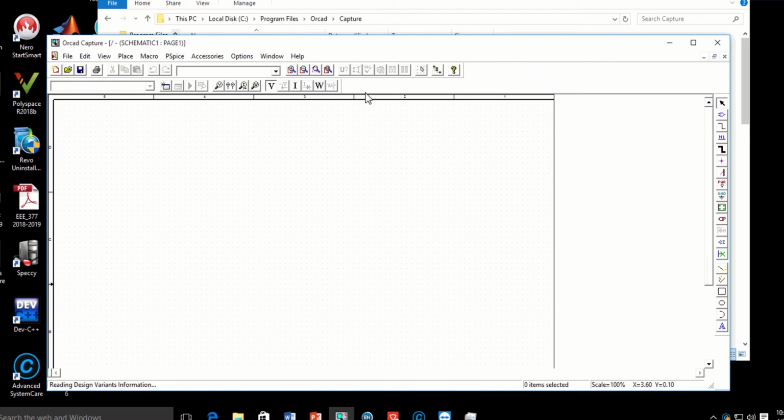Generally, after the first interface is successfully created, the next steps are to place components, connect components, label wires, and run the circuit to perform PSpice analysis. To simplify all the general steps, as I mentioned earlier, we will use a simple DC series circuit as shown in figure 2.8 in your notes.